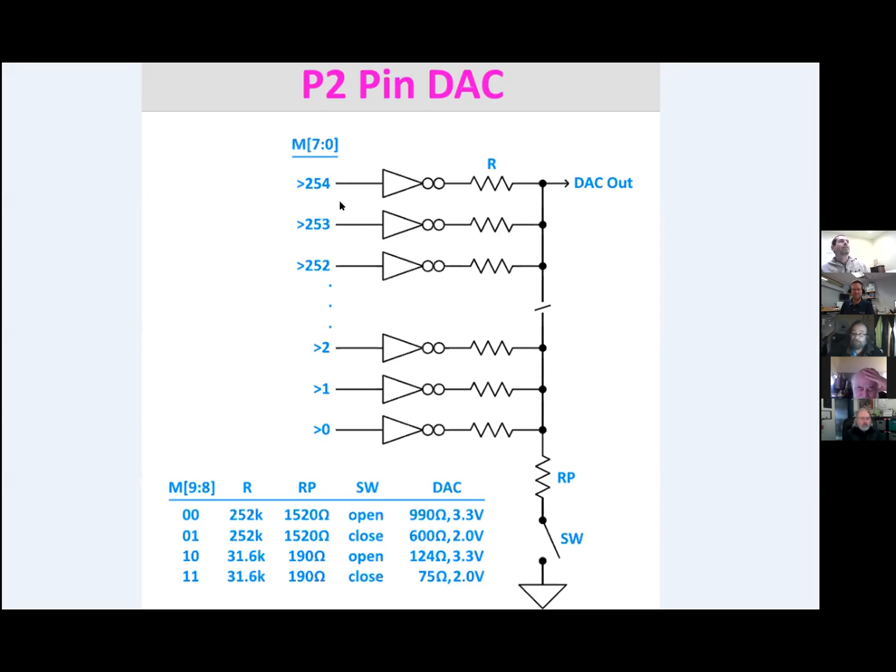Chip, I'll look forward to reading your documentation to see if I can finally understand the thermometer. Well, just imagine it going up and down. Take any inverter in this thing, and wherever the level is, everyone below is outputting a low and everyone above is outputting a high. That midpoint moves around depending on what value you write. So you have a tug of war going on. Some are outputting low, some are outputting high, through those resistors.